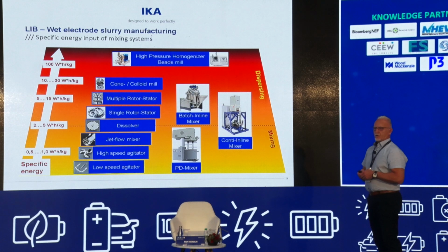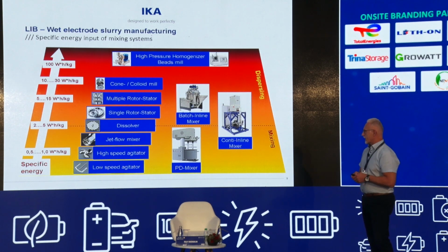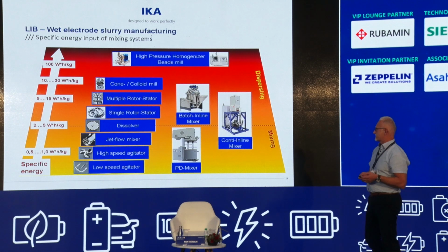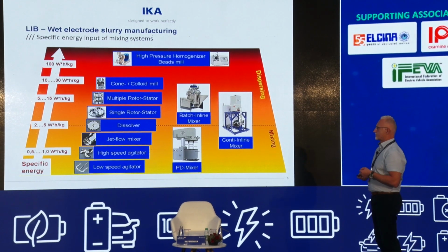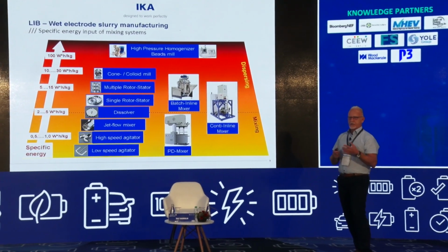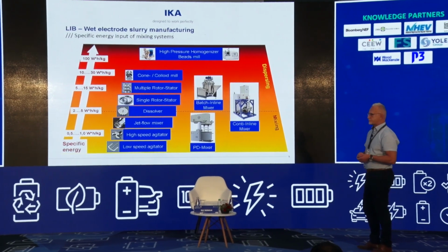Here's a quick overview about different mixing systems. And here you can also see the specific energy input. So it depends on what the material is and what energy level I need to get the particles single and well mixed. Based on such requirements should be the selection, as you cannot achieve a good quality when the energy input is not given by the selected mixing system.